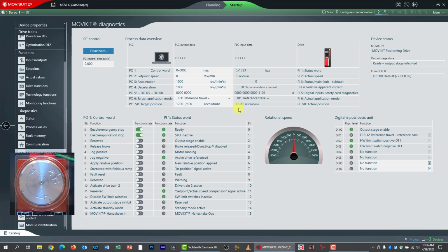So we are plus 12 revolutions, in other words, clockwise, of the actual machine 0. If I changed to a travel mode and did go to 0, my drive would run counterclockwise 12 revolutions until it got to 0. In fact, let's just do that for fun here.